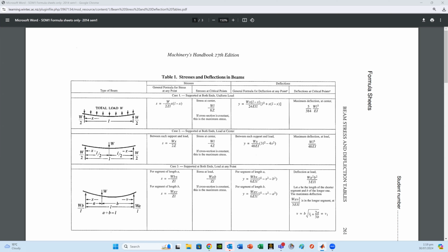Let's run the script and see if everything is going well. So now the stress is replaced with the values to represent the stress calculated. So we calculated the stresses from one end to A and from the other end to A again, but we're taking two different segments for it. Okay, these two are what we call the stresses due to point loads in the short section and the long section. Okay.